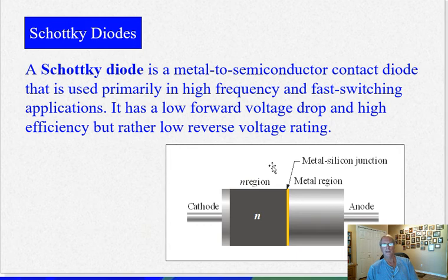They do clamp. They are used in clamping circuits for voltage regulators, or steering currents in voltage regulators and switching voltage regulators primarily. But these are very common diodes, used a lot. The thing to remember about Schottky diodes is they've got a really low forward voltage drop, which means it's highly efficient. You don't get that 0.7 volt drop. It could be 0.1 volts, 0.2 volts. That's it for a Schottky diode.